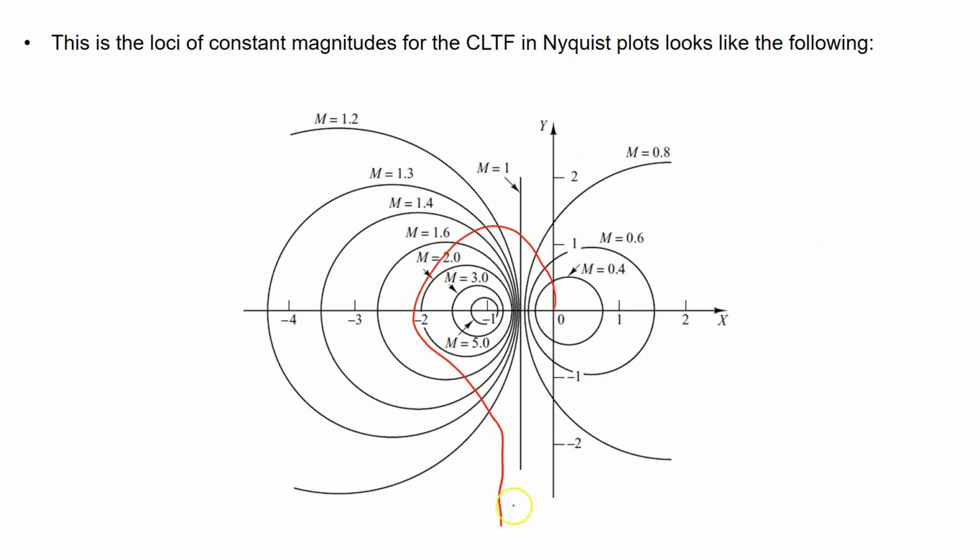So when you see a Nyquist plot like this, as I said, if this is for a gain in the compensator, gain of 1, now if you make gain 5 or 6, you do not see a simple change in this graph. It's not like, well, this might be just shifted so many units up or down or left or right. Okay, so you cannot say, well, this is for k equal 4. That is not correct. It's not going to be simply shifted up or down. It has to be redrawn completely.